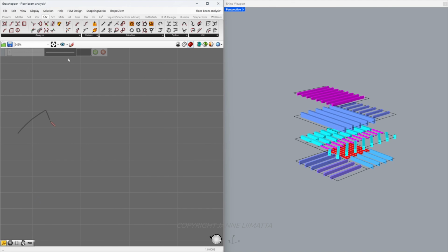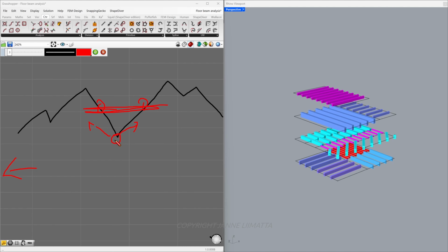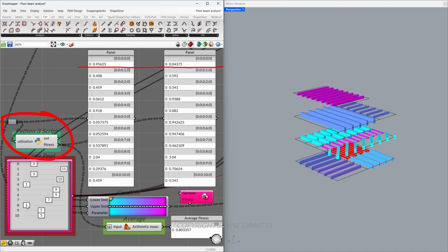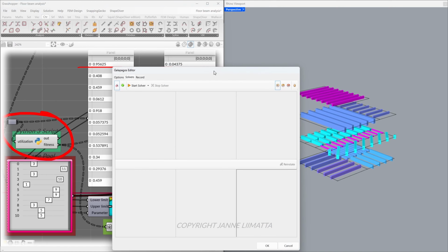To better explain this, we have different values like this for our bending resistance. Our best value is here that we got from the analysis. The actual best value would be somewhere there. And if we're trying to check close to this, we have arrived at a local optimum because both of these values are still worse than this one. This is a common pitfall in genetic algorithms, so please keep this in mind. If you get stuck like this, you can manually help the algorithm a little bit until you arrive at the better solution, and then continue with the solver.